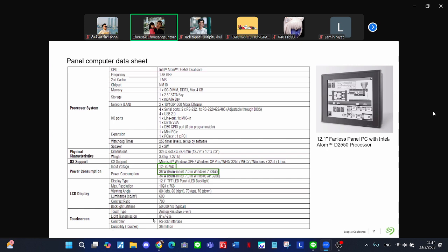The computer's input voltage is 24, right? And power consumption is 36. We calculate back. The current is power divided by volt, right? So the current multiplied by a safety factor of 25% becomes 1.875 here. And for the circuit breaker, you can select from the closest value.